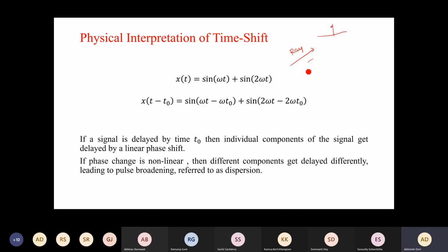Now what would happen? Let us say that we have a medium. One situation is I shine a ray of light and this ray of light arrives at the output just as a ray of light. The second situation is that, because of different properties of the channel, this ray of light begins to take different paths. A part of the ray goes like this, a part travels like this, and a part travels something like this. If the propagation speed is the same, but they are taking different paths, they will arrive at different time instances. So an impulse transmitted through this medium, with its energy distributed over different paths, will get broadened.